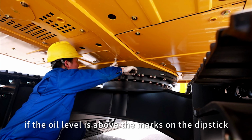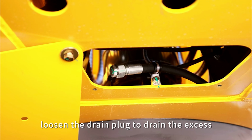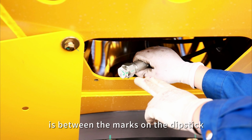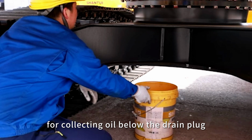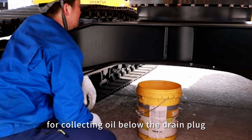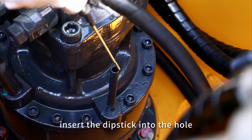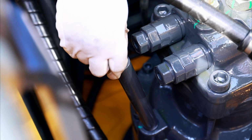If the oil level is above the marks on the dipstick, loosen the drain plug to drain the excess gear oil until the oil level is between the marks on the dipstick. Before draining the gear oil, place a container for collecting oil below the drain plug. After inspecting the oil level, insert the dipstick into the hole, and then install the oil injection cap.